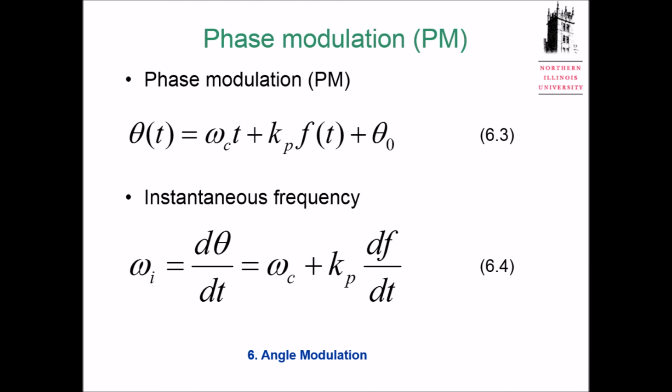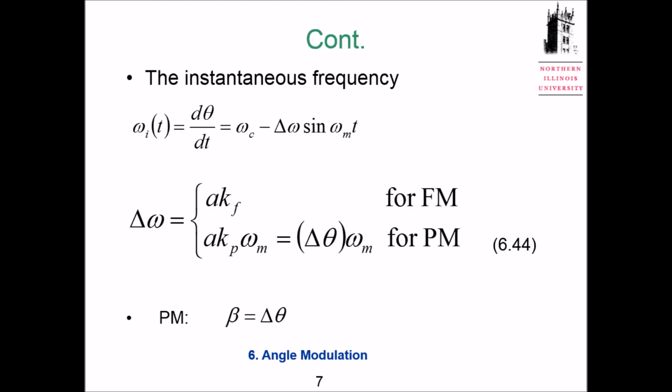the function of your instantaneous frequency to your message. So now we go back to this. For FM, peak frequency deviation is related to your signal's amplitude, also the constant, the linear constant, like the slope, right? For PM, it is related with A, the same.